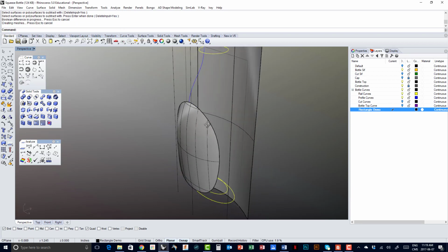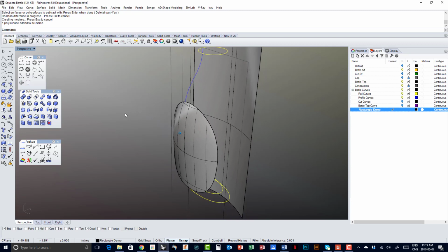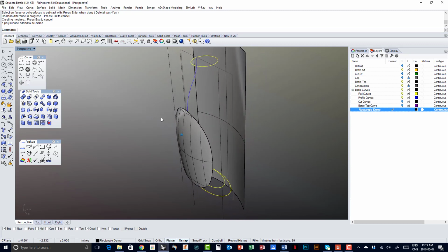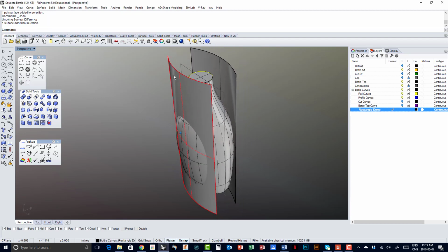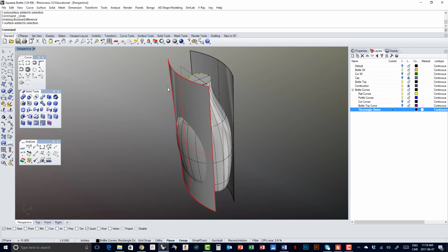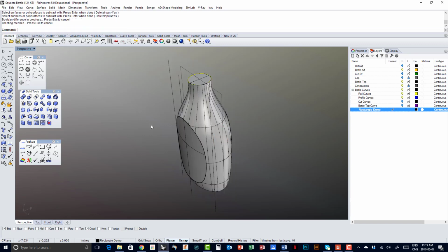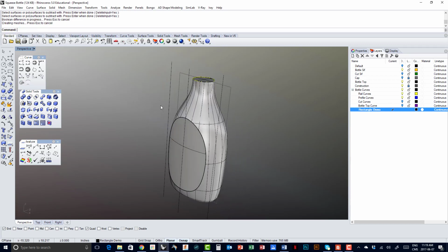And now it gives you a result that's not what you expected, okay? So again, I want to re-emphasize, whenever you have surfaces and you do a Boolean difference, if you get an unexpected result, it's very likely because your normals are not pointing in the right direction. So I just need to click on Analyze Direction here, and I just left click and then right click, and I've changed the direction so that now when I do a Boolean difference, I select my solid, enter, and I can select both surfaces at the same time and then enter, and there you have it. Okay, it did the difference.